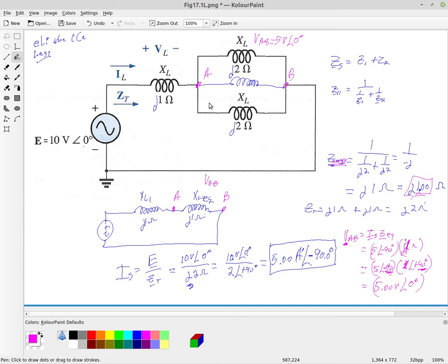All right, so given that, we can find the current through one of these inductors using Ohm's law. We know the voltage, we know the reactance, so we just apply Ohm's law. Sorry, that can't be a 1. This was a 1 over here. This is our second inductor, L2. So XL2, so our current for inductor L2 using Ohm's law: current is equal to the voltage.